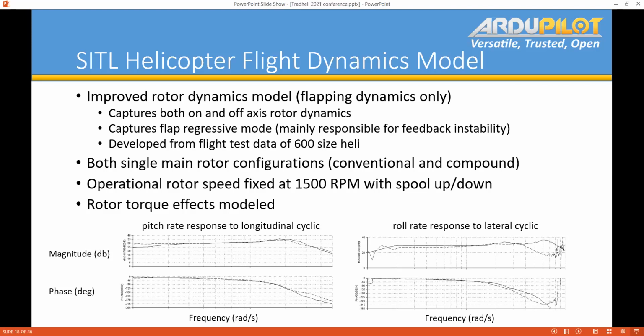Sure. And this is a plug for Leonard as well, as far as using the frequency response, essentially the new SysID mode that was developed. Basically, you can use that SysID mode and do frequency sweeps, essentially oscillating the aircraft side to side or forward in one of the axes over a range of frequencies that you're interested in learning the dynamics on.